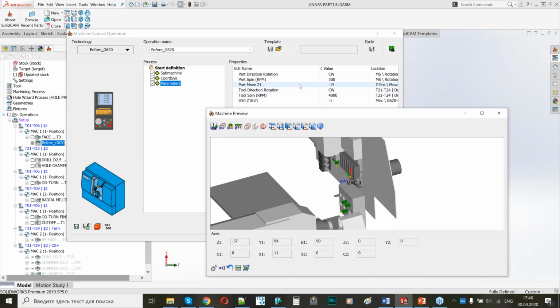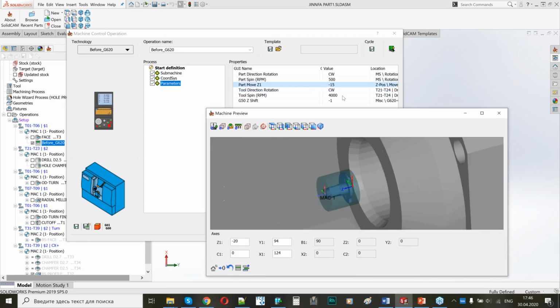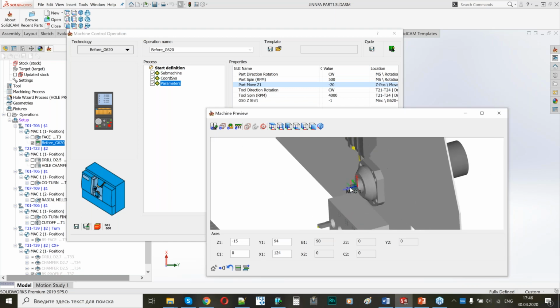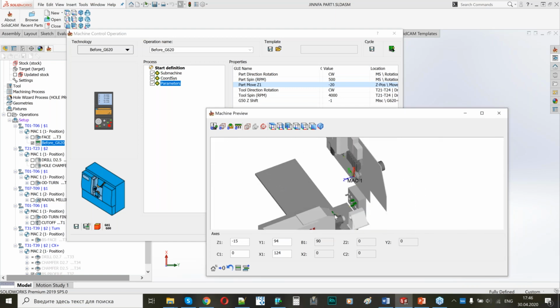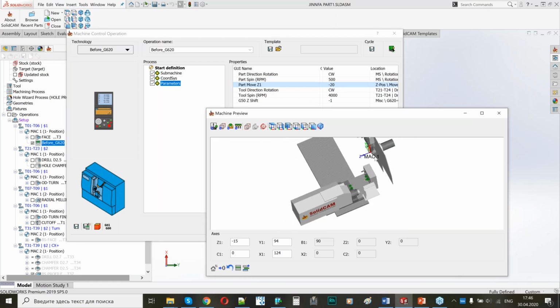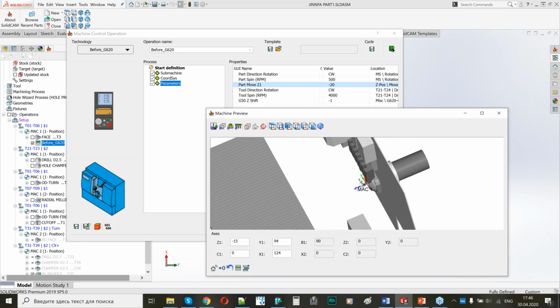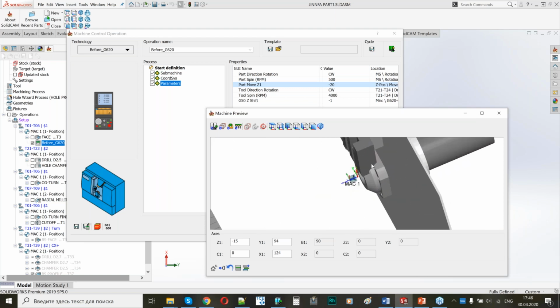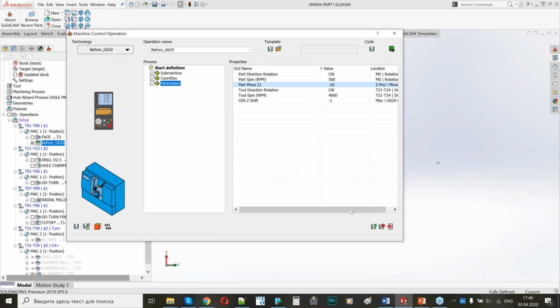I will have this position here, and I would like to change it and apply 20 millimeters. So the stock goes out from the guide bush, and then these tools go to the stock, and the stock is not moving, only the back spindle with these tools moves to perform this drilling operation. It's a very nice feature, very nice operation. It is used for deep drilling.